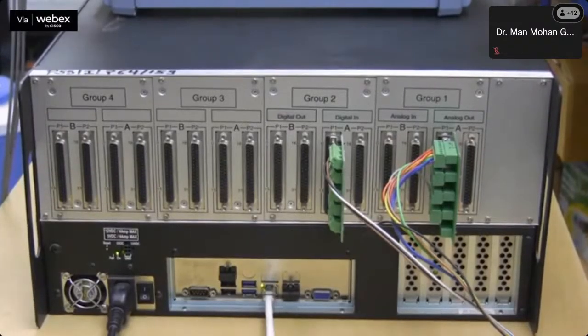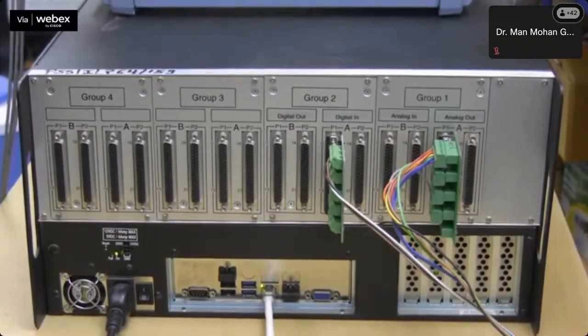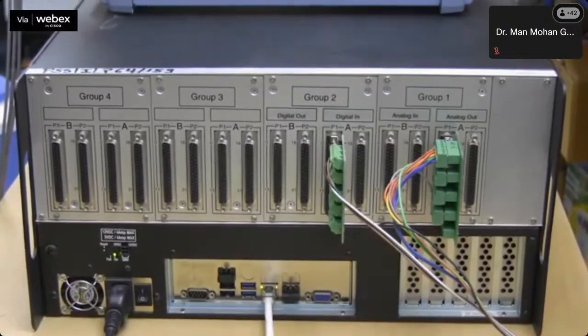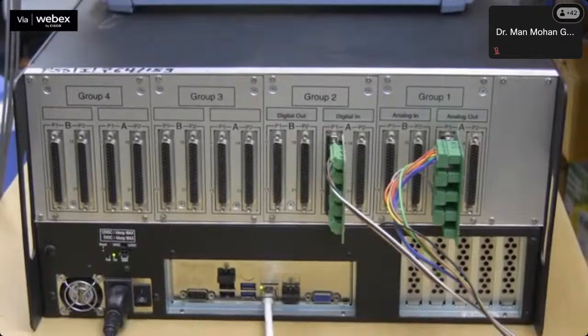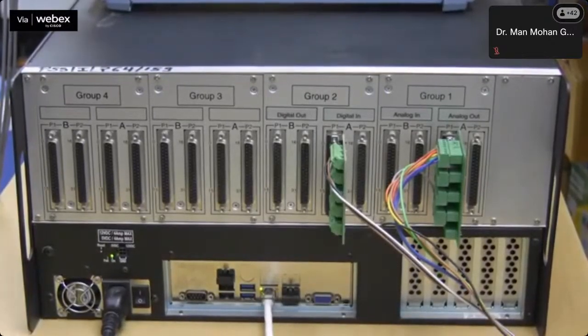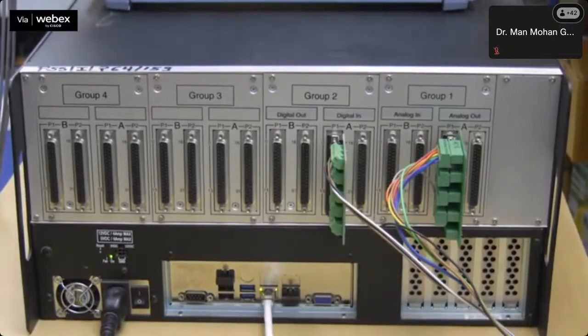As we can see, for our experiment purpose, we have used 7 analog out signals with a ground pin and 3 digital in signals with a ground pin connected through a DB37 channel. After setting up the connections as per the block diagram, let us understand the simulation platform of both OPAL-RT and TMS board.